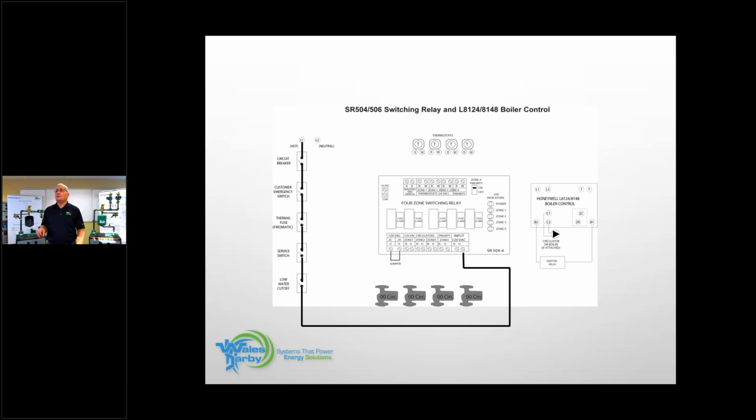The switch in the red box, all right? And if there's any other type of switches, and also the circuit breaker from the panel, that's incoming power. And we're bringing it to the panel, and we're bringing it to the relay that's right on the boiler, okay? So that's one side of power, and then we have to do the neutral side, okay?